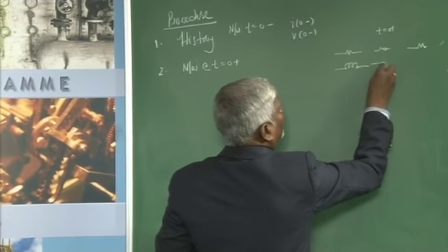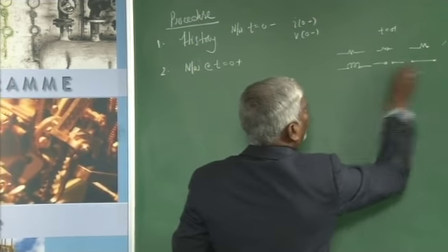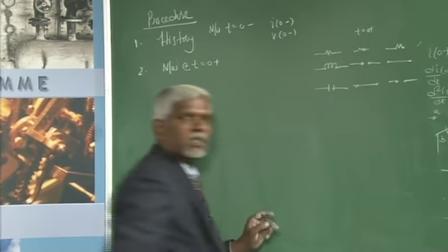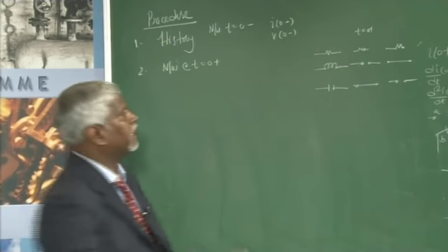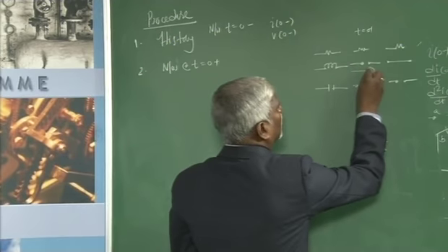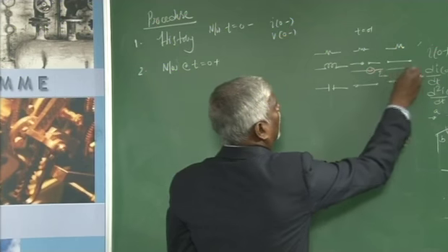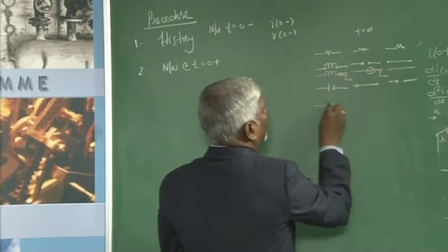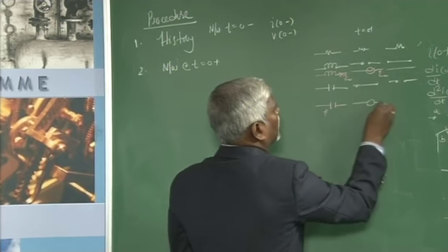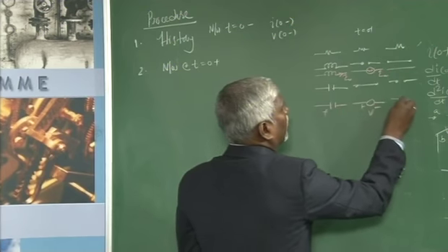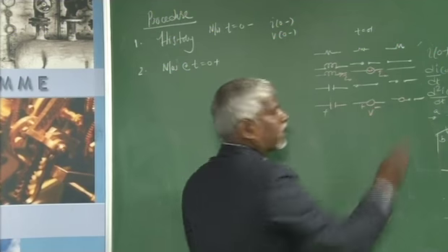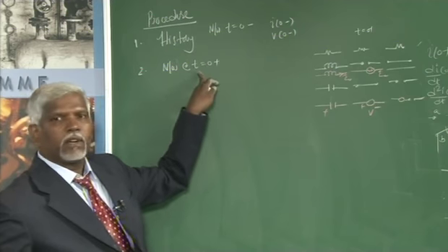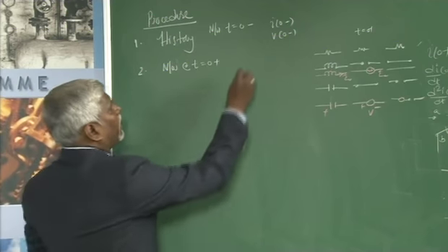An inductor acts as an open circuit and finally a short circuit. A capacitor acts as a short circuit and an open circuit. With this in mind, if there is an inductor with initial current I naught, it acts as a current source I naught, and finally as a short circuit. Similarly, a capacitor with initial voltage acts as a voltage source V, and finally as an open circuit. With this in mind, what we saw previously: find the network at t equal to 0 plus,